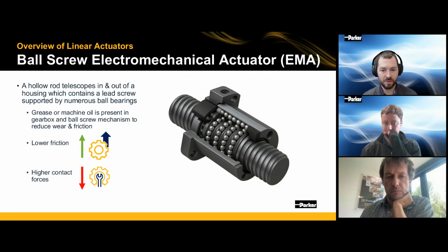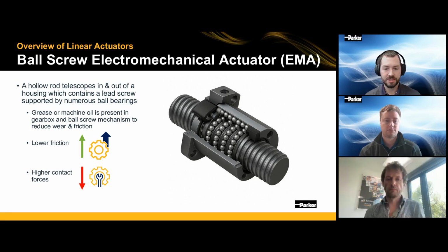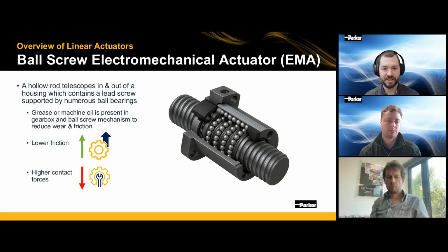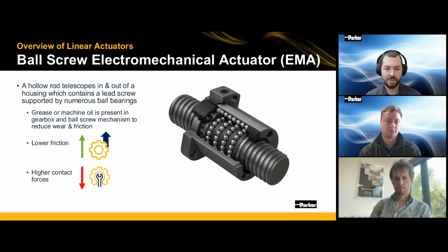However, those series of balls, because of the motion that they roll through, do tend to fatigue and are not necessarily as reliable in high shock or vibration applications, and are likely not to last as long on a lot of mobile equipment where there's longer lifespan requirements, or the person's going to be operating the machine in a harsh application with shock or vibration.